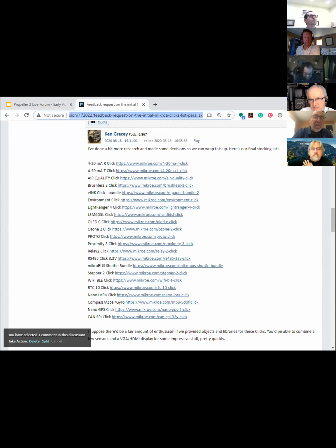I'll just pick 3 or 4 modules, one I2C, one SPI, one serial, so I can mix and match. Right. Another option is just to use the Spin object too. Sure, but I already have I2C and SPI working and serial works. So it's just a matter of writing little C demo programs that talk over SPI or serial or whatever to these modules with the appropriate pins.